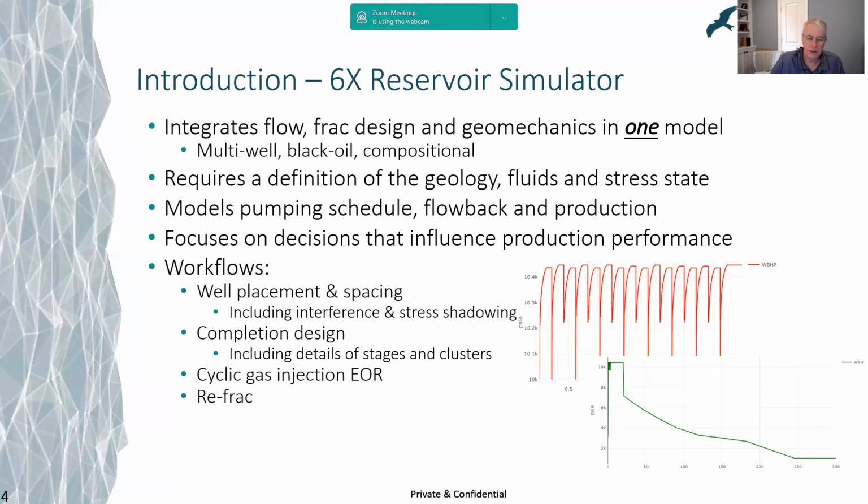We also use a definition of the fluids, which can be the black oil PVT or a compositional equation of state. And we put in the initial stress state. We then model the injection rates from the pumping schedule at the times and at the locations along the well where the stages were actually fractured. We then model the flowback of the frac fluid and the long-term production.